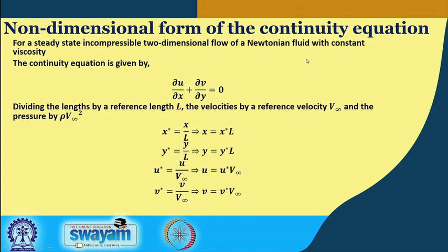Now all these phrases should be noted very carefully, because depending on what we assume, our balance equations will change. So because of the steady state assumption, we will not be having any time differential in the equations. Then because of incompressibility, we shall be having the density to be constant. So we can take out the density from any of the differentials.